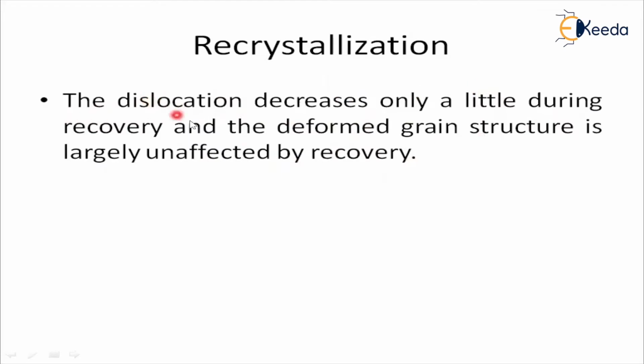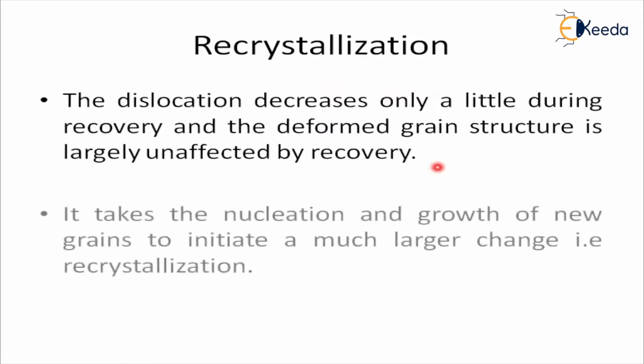If recovery is already reducing the stresses, why is recrystallization needed for every material? Because recovery reduces only a little of the deformation. So that's why recrystallization is needed. And you can observe the last sentence here: the deformed grain structure is largely unaffected by the recovery. So that's why recrystallization is needed.